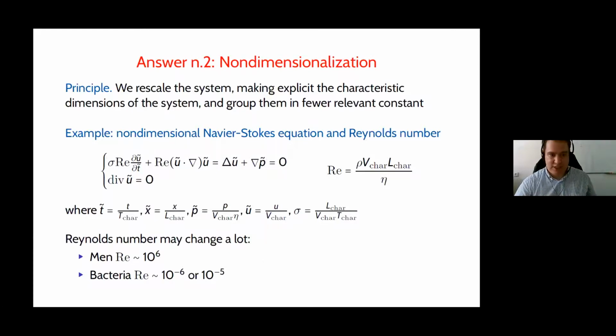And this again is important in locomotion. You can compute the Reynolds number, for instance. It measures basically the ratio between the inertial forces of the fluid against the viscosity of the fluid. So if you swim, the liquid's viscous properties are more important than inertial properties.